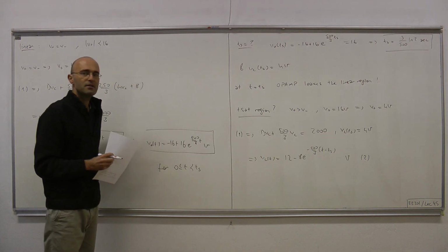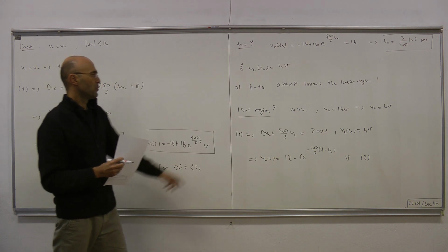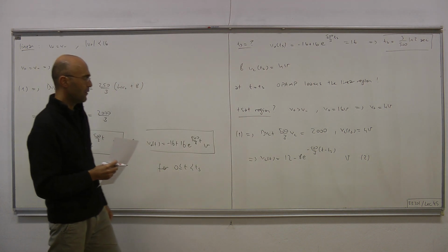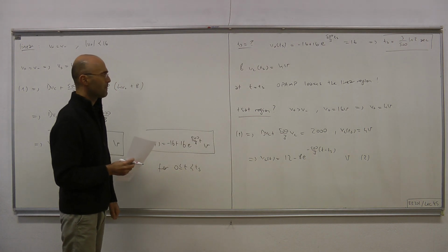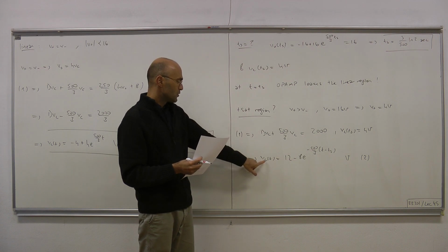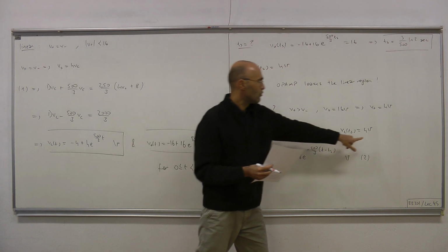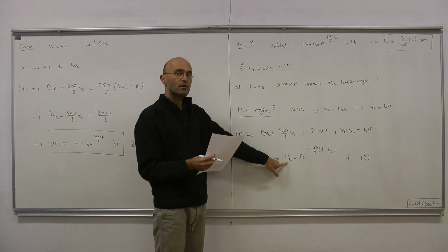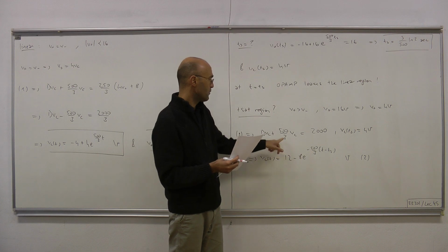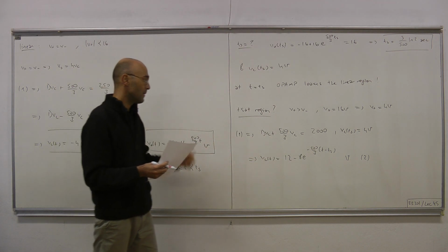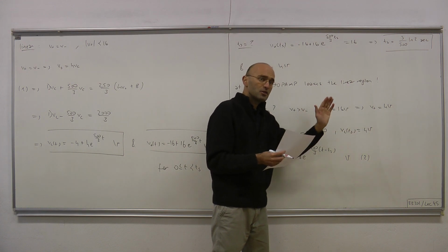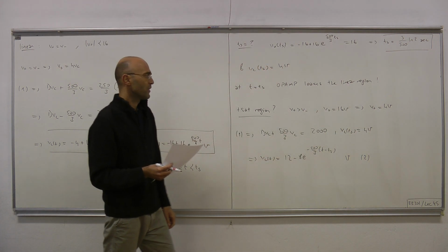Now let's try to interpret whether that's possible, whether the op-amp can remain in positive saturation region. Now, this is VC(t), and remember that VC(t), the capacitor voltage, is same as V minus. So VC(t) starts at 4 and it's heading toward 12 because this term becomes smaller and smaller as time goes on, because now we have natural frequency negative. It's instantaneously at 4, but just after that it becomes larger than 4.